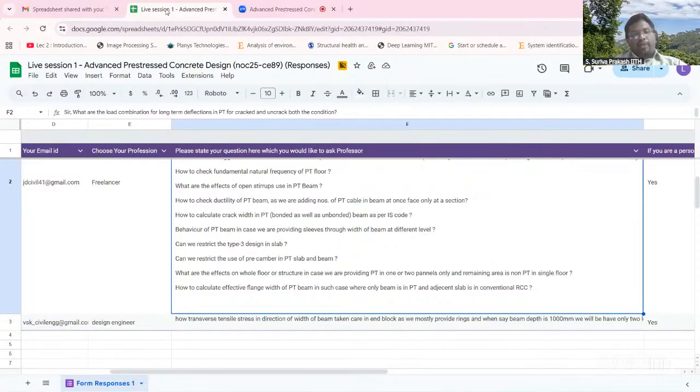Now we are evaluating that section, right? Then what we have to do is the moment curvature analysis that we have discussed. Then you find out the strain at the soffit, at the bottom of the beam. And typically crack width is the strain at the location multiplied by the crack spacing, S. Now, how do you get your S? S is determined by some empirical formulations, okay?